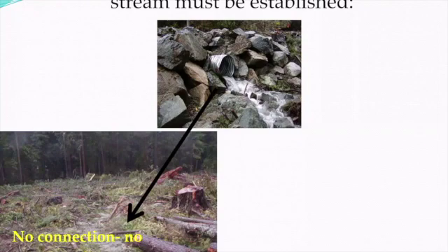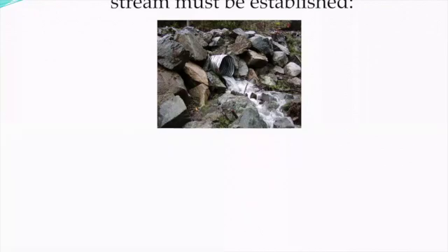The coarser material will drop out of the water in the first 5 or 10 meters in the slash, and the finer material, if it is hummocky ground, will drop out again within a further 15, 20, 30 meters. There is no change to the hydrology of the site, nor change to the water quality, because the sediment and water is being reabsorbed into the soil.